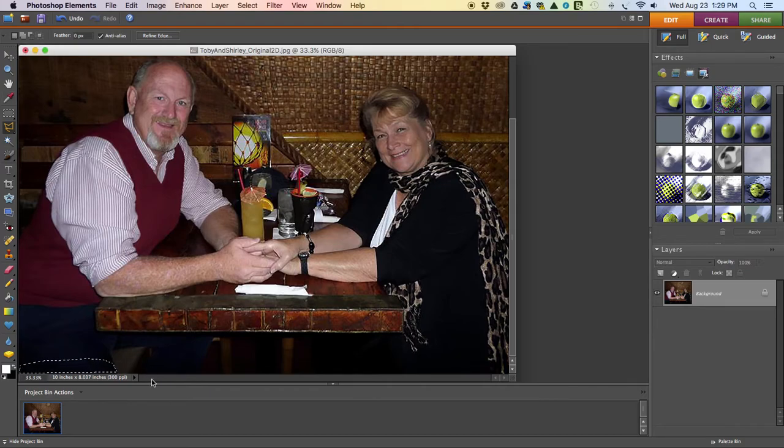And with the default, if I were to try to click in and create my second depth slice, what happened? It erased my original selection lines, and I don't want that to happen. So I need to choose Add to Selection, and that enables me to create a new depth slice.